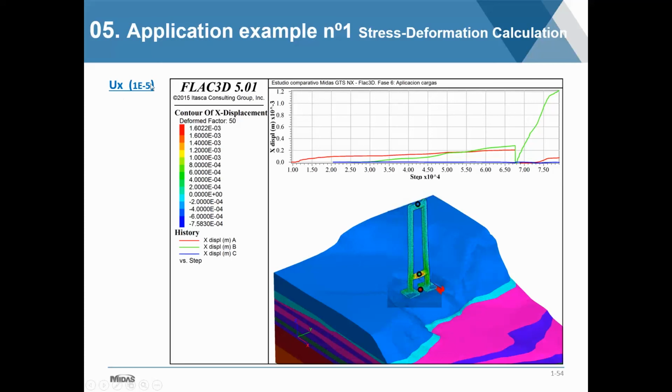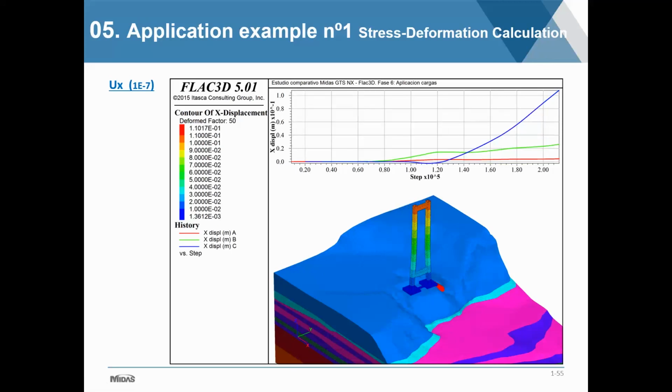So we see that by the default solver ratio criteria, the program stops here, and even looking at displacement graphs or on the model, it looks, even in the range of values, like it has stopped prematurely. If anything, the displacement still seemed to be growing in the direction where the load is applied. And so we don't really know what the final values would be.